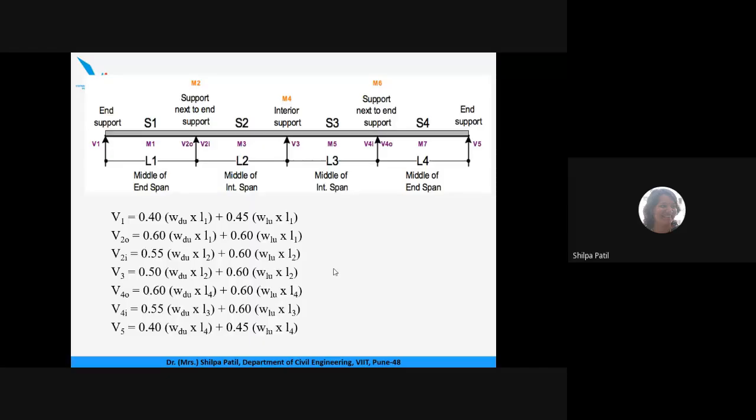The process is same. If you identify a given slab as one way, the process will remain same. If you identify it as two way, the process will remain same. But the number of one-way and two-way slabs with different dimensions will be there. Each and every slab you need to design separately. If you have a same dimension, the one design will be sufficient, and the same design will be provided to another slab also having the same dimension.